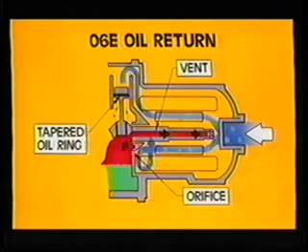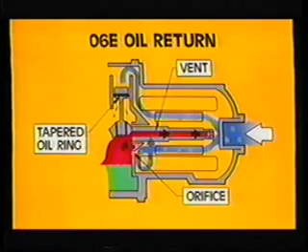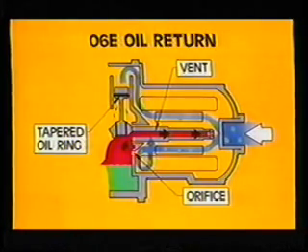The high-velocity suction gas which enters the motor housing does not allow the oil vapor to separate out as it does on the O6D. The gas and oil mist is drawn directly into the cylinders. A unique tapered oil ring is used to scrape oil off the cylinder walls and return it to the sump. Because the oil in an O6E is being returned to the sump by the rings, it's not necessary to maintain sump pressure below motor housing pressure.